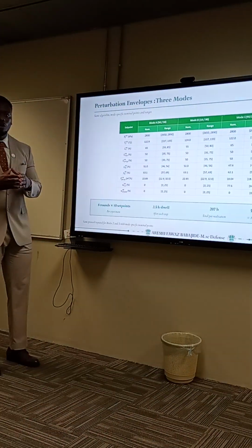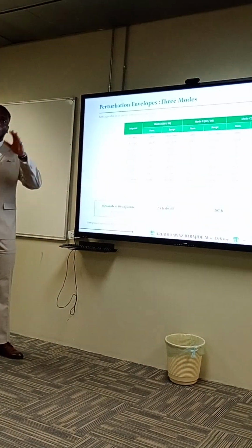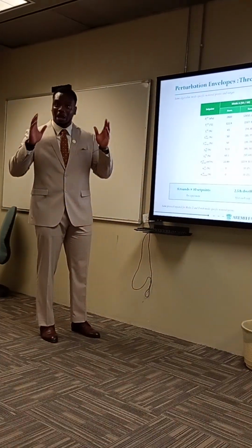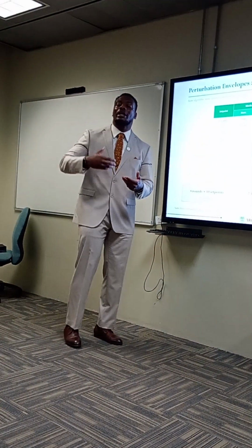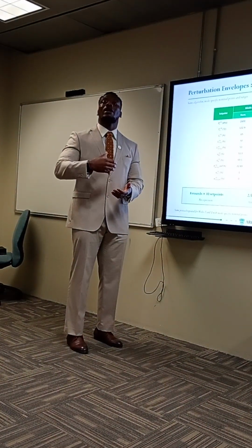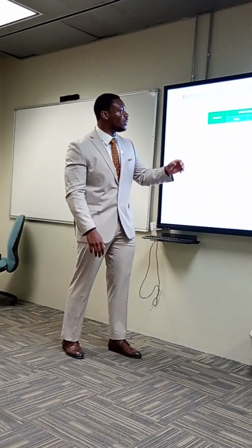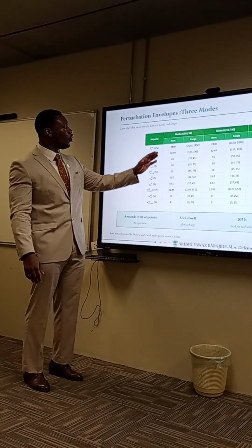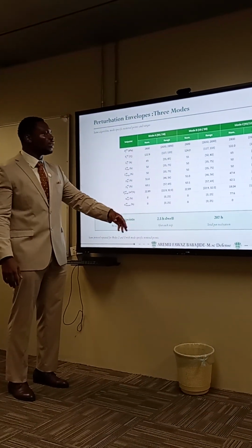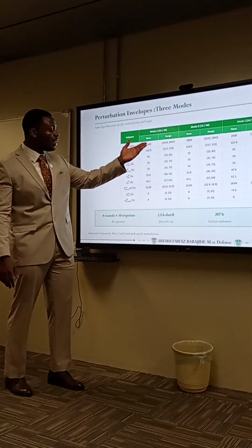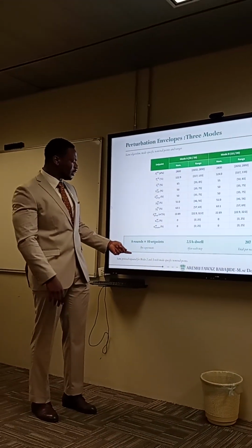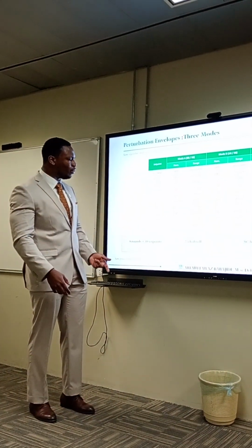And mind you, pay attention, we're not going through all the variables, we're just looking at economic variables, because we are trying to make sure that the decisions in our plant are determined by the economics of the plant. So of course you have 2,800 at nominal, and then this as the range, and we have several perturbation ranges. We have about 8 levels of strata, 8 divisions for each of 10 set points.